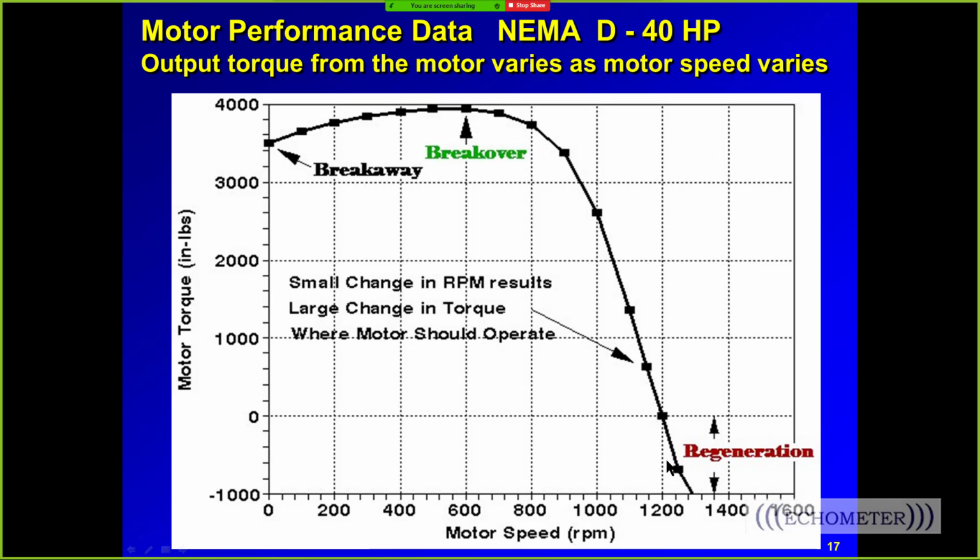And then for a conventional unit, you'd be maybe generating motor energy at the very beginning of the stroke, and then you start to provide power to lift the rods, and the KW is going up and the motor slowing down. And then you get about halfway up, and then the power required is reduced, and then you get to the top of the stroke, and as the weights fall to the bottom, you generate power, and you're going faster than 1200 RPM, and that's a negative KW that then goes out on the power line, and then the power company sells it back to you on the downstroke.